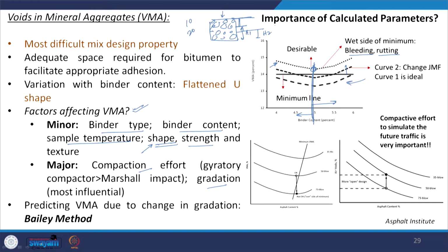So, further the mix will get compacted and you can have more reduction in height, and let us say this is H2. So, you see, when you apply a compactive effort, you are actually preparing a bituminous mixture here. For example, in the first case your bituminous mixture will look like this, is it not? In the second case your bituminous mixture will look something like this.